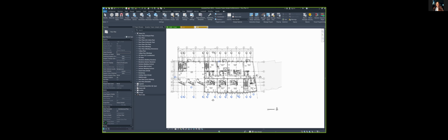Well, if I wanted to do that, I would do that as IFC. Because IFC, okay, firstly, let me just set a disclaimer. Anything that is not native to Revit, you're not going to have 100% compatibility. So maybe it's an issue with a section, or maybe it's an issue with labeling or alignment or whatever. If it's not native to Revit, you might have some issues.